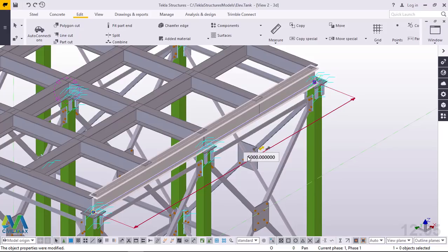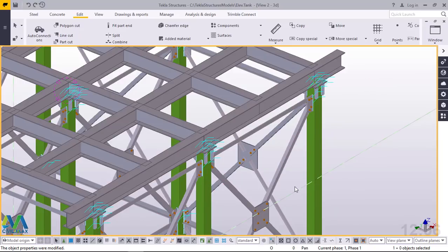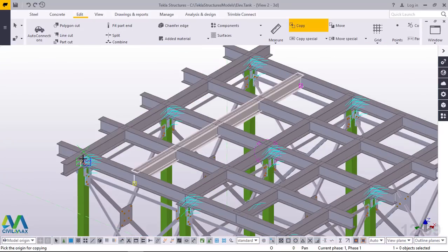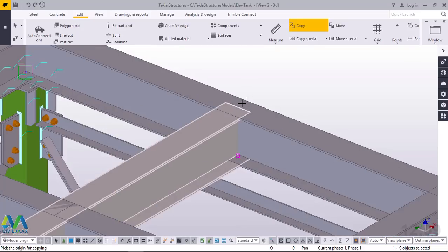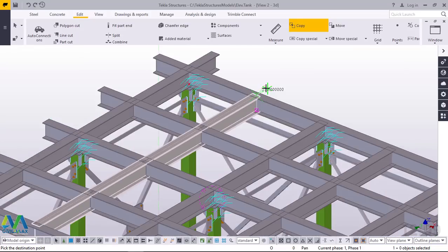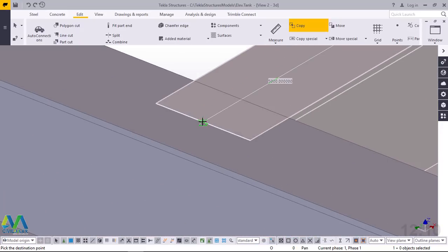Then I'll select this dimension and feed in. Let me just remove everything first, and I'll type 1600, and I'll press enter on my keyboard right here, and you'll see both ends extending. There we are. And I'll do the same thing at the other end. Click on that and click on this to just make work easier for us, and we'll just snap at the center here, and hold it from that, and connect it up with this.